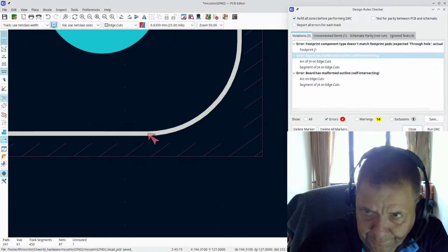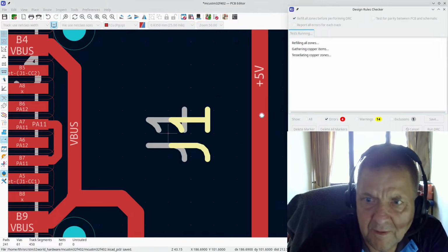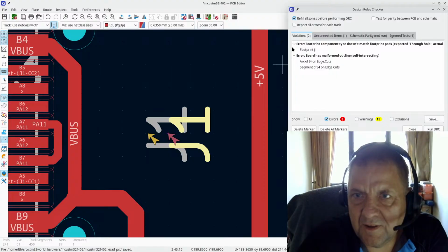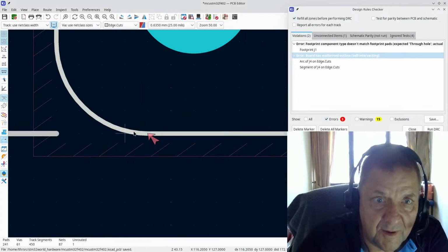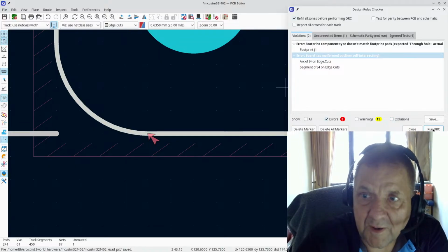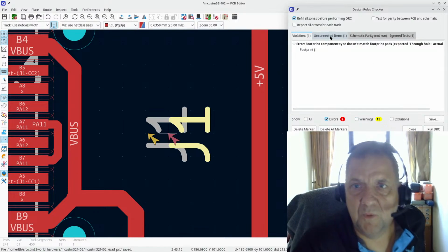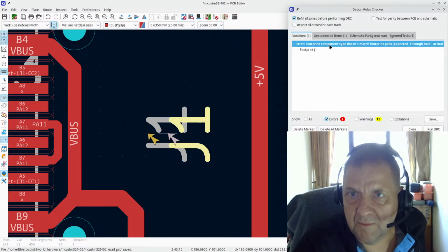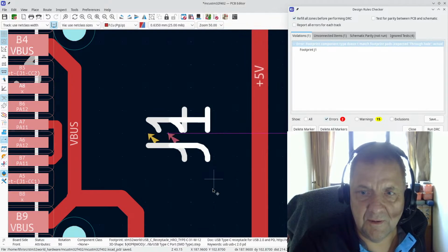So what is happening here is the edge cut. I actually defined the edge cut in the footprint, and I defined the edge cut obviously on the original board, but I didn't update from the footprint library from that one, and that is why we ended up here. So now we are back with that one problem with this particular footprint.